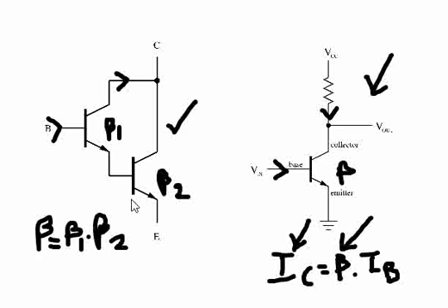So this circuit is actually used in power amplifier circuits or audio circuits. Many applications are there for these circuits. Now, an important characteristic of these transistor circuits is the input impedance. Input impedance means the impedance seen by the circuit that is connected to this amplifier circuit, and it is high.